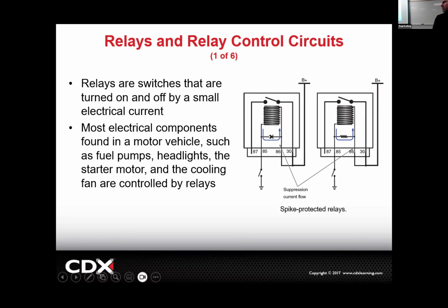Now part of this point is we put a little diode right here because when you're magnetizing and unmagnetizing, sometimes it can make a little voltage spike. This allows for the current to basically drain back. Make sense? It prevents a spike, but also, you could figure it like this more simply: electrons don't get trapped in there.